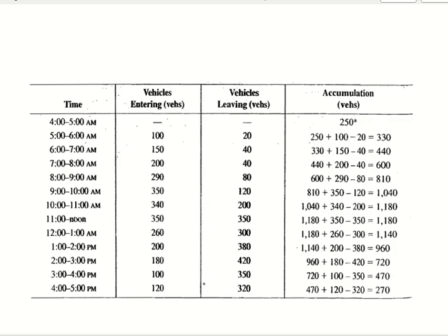Okay, so we start when these two are not changing much, so this will be almost a constant number. Even if you miss 2 or 3 vehicles, plus or minus, it doesn't matter, you are getting almost the same thing. Clear? So the first count is basically for vehicles which are already in the area. They are parked somewhere or they are going within the area on some streets, you will count them. Clear? Then the real counting begins for the vehicles entering and leaving.